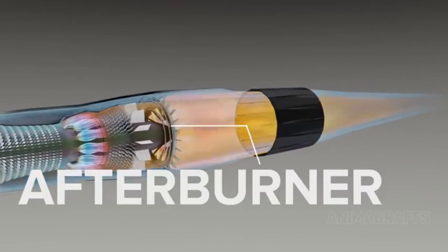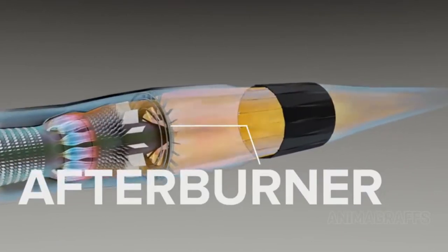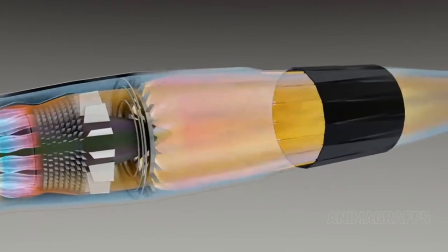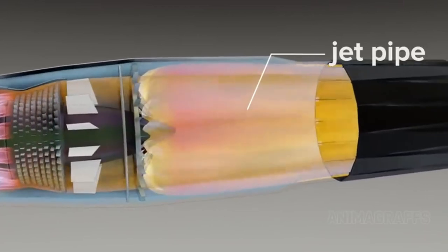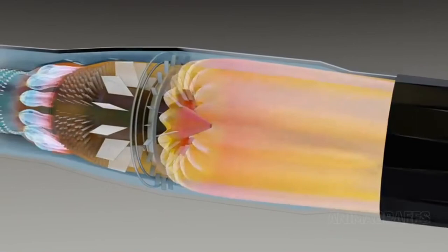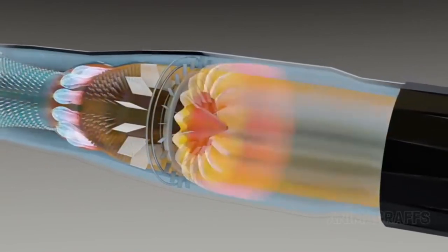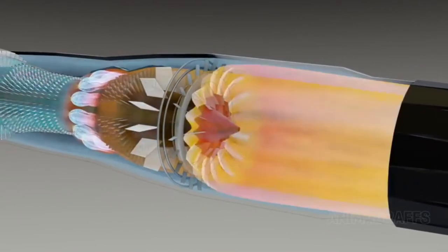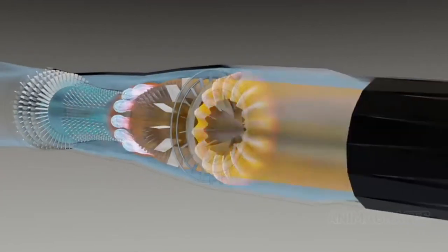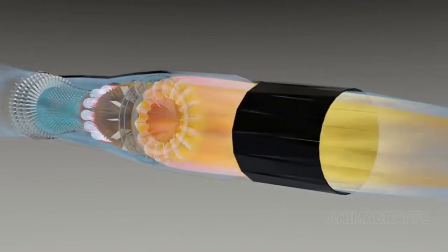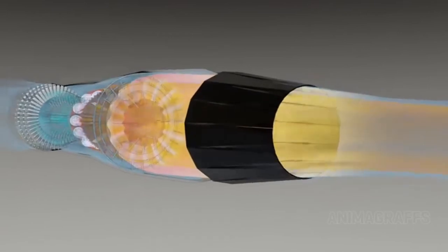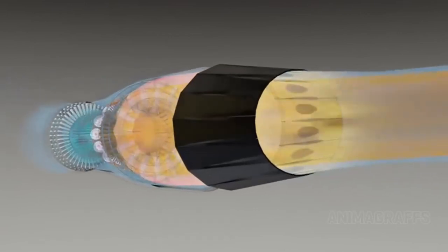Afterburner. High-performance engines may have afterburner capability. Additional fuel is sprayed into a jet pipe section where it mixes with exhaust gas and is ignited, producing a second stage of combustion. Since afterburner is fuel inefficient, it's generally used in short bursts during takeoff, climb, or combat maneuvers. The exhaust nozzle is adjustable for maximum exhaust acceleration and to avoid undesirable back pressure, which can harm forward engine parts.